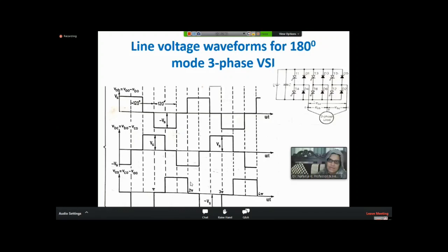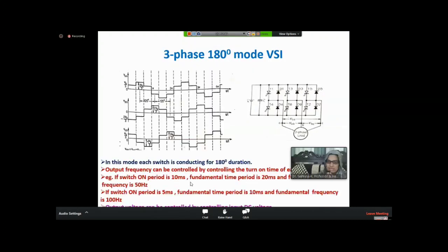Varying the frequency alone may cause problems when it is operated below the rated speed. You have already seen in the previous modules that you can operate the induction motor below the synchronous speed in constant torque mode.